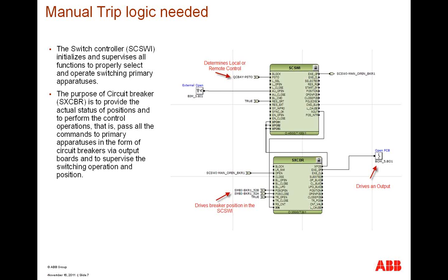It's binary input number 1 that correlates to 2 stud numbers on the back of the relay, studs 1 and 2 in slot 3. And we have an output coming out of the SXCBR. This is what will issue the external close command to the circuit breaker.